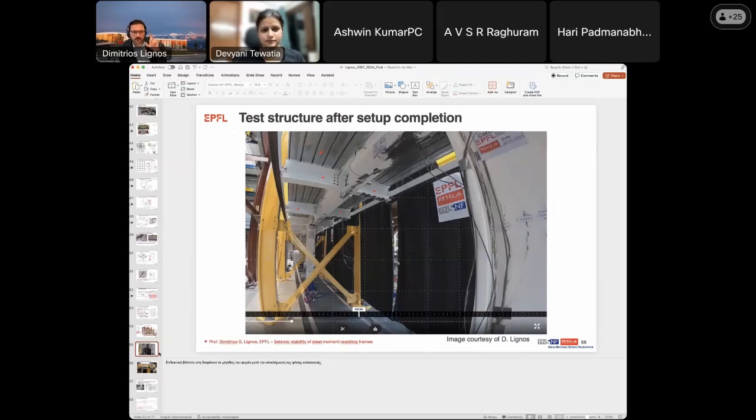But the good thing about the transverse beam is that it works like a restrainer in the panel. If you have a shear distortion in the panel zone and the panel zone deforms a lot more than you anticipate, then if the column is very slender, you may worry that you may get shear buckling in the panel. But the transverse beam, because it separates the panel into two web panels, works like a restrainer, and in fact, it will help the panel not to experience shear buckling.